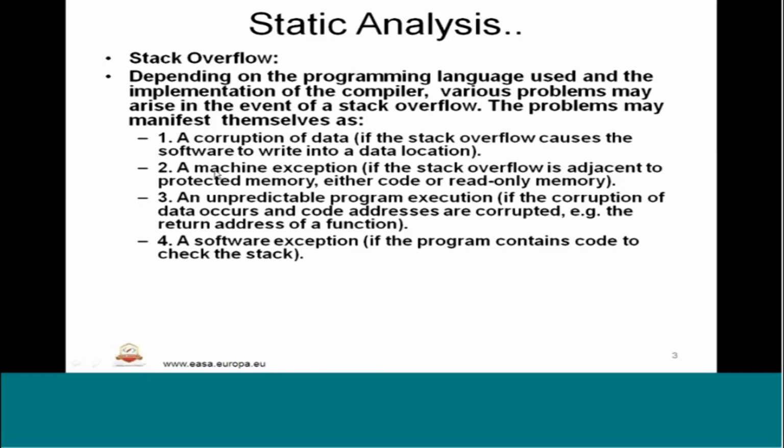So what are those? First, a corruption of data. If the stack overflow causes the software to write into a data location, definitely we are going to have an unintentional write into a data location, and that can cause corruption of the data. Second, machine exception, because the stack overflow is adjacent to protected memory and we are trying to write to or access the code, which is read-only memory. Definitely there is an unwanted exception for this.